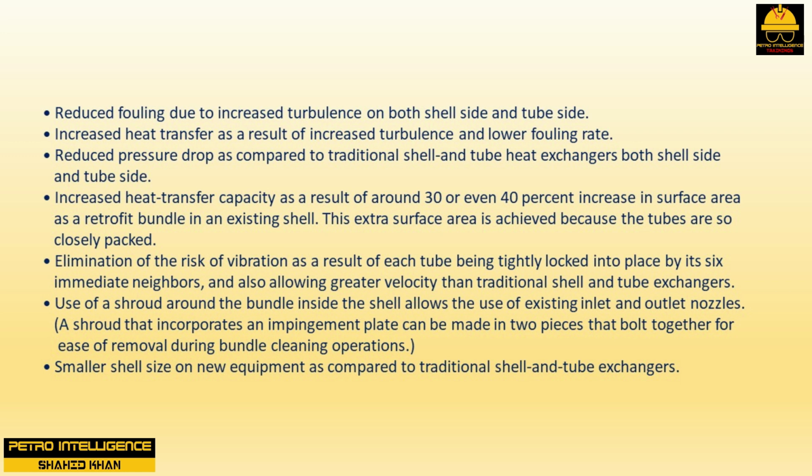Increased heat transfer capacity as a result of around 30 or even 40% increase in surface area as a retrofit bundle in an existing shell. This extra surface area is achieved because the tubes are so tightly packed. Elimination of the risk of vibration because of each tube being tightly locked into place by its 6 immediate neighbors, and also allowing greater velocity than traditional shell and tube exchangers.